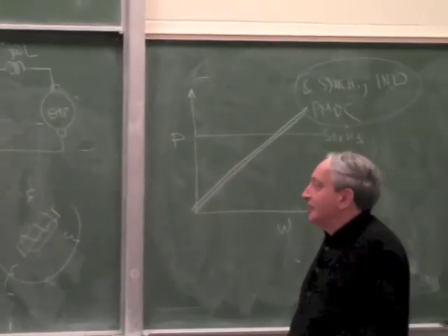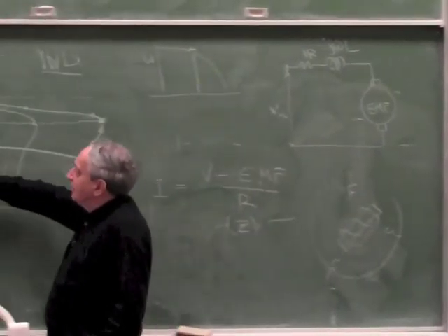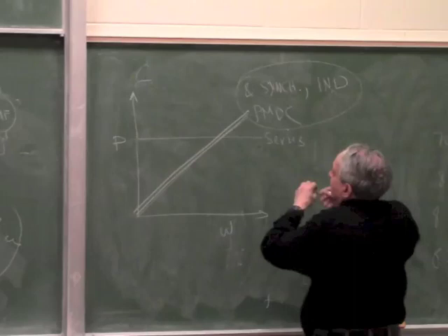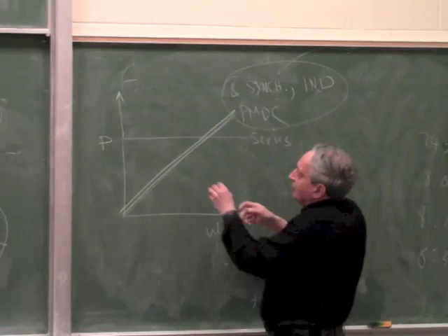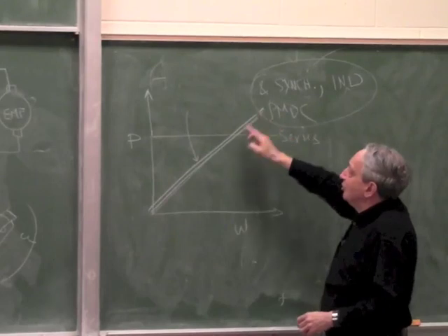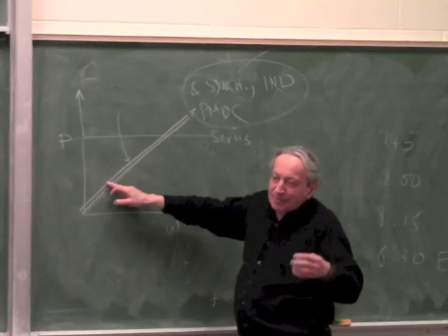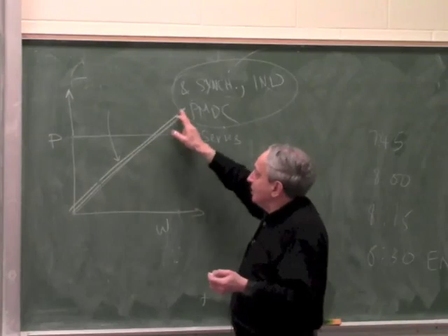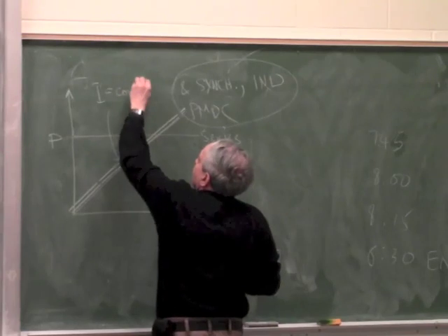Now, because of the need to change the voltage when you change the frequency, you cannot keep this graph on forever, because this graph implies you could go on forever, since this graph is still under constant current. So when you run the motor here, it doesn't get any more hot than here. Because what heats up the motor is I squared R, plus a bit of air friction, plus a bit of hysteresis, but the main reason the motor heats up is I squared R, and we are keeping I constant. All these graphs are under the assumption that I is constant.